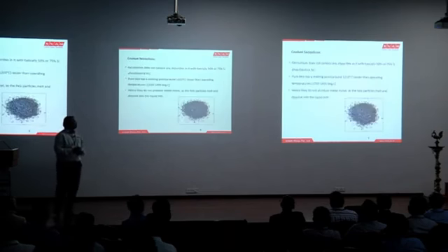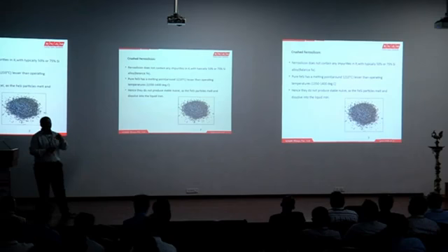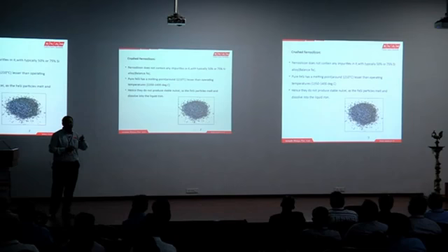Next is ferrosilicon. Ferrosilicon is a silicon source for the cast iron industry. They add ferrosilicon to increase the base silicon content to meet the required desired properties, like it can be a grey cast iron or a ductile iron.